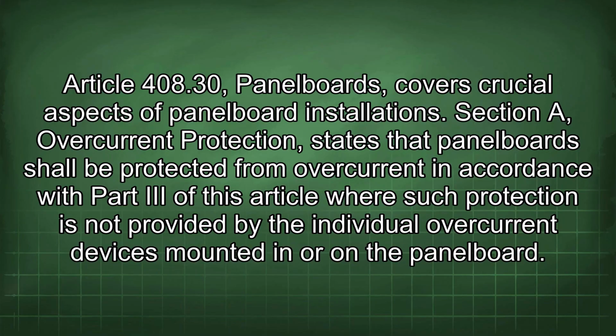Article 408.30 Panelboards covers crucial aspects of panelboard installations. Section A, Overcurrent Protection, states that panelboards shall be protected from overcurrent in accordance with Part III of this article where such protection is not provided by the individual overcurrent devices mounted in or on the panelboard.